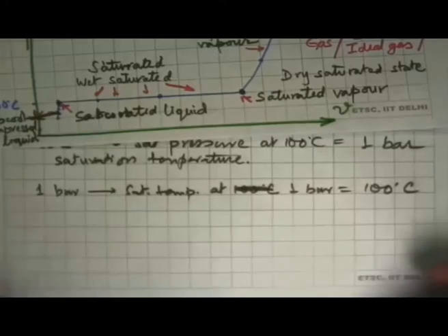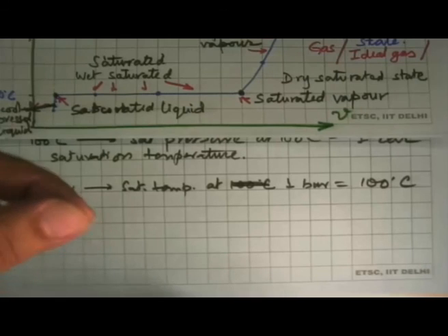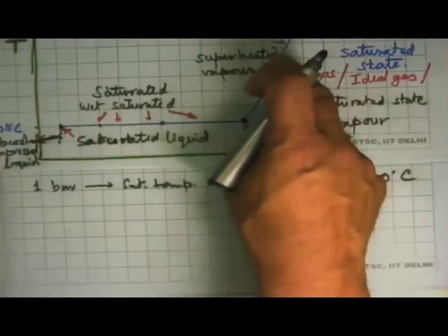And now we say, well, what happens in the other cases? So for this, one only needs to go to a table, and these properties are well documented, and you say, look, for this material, this is the pressure, this is the saturation temperature. And the pressure in this case is 1 bar. In a minute we will see what happens if it is 10 bar, 0.1 bar, or if the substance is different, everything will fall in place. What we will define now is, well, compared to the saturation properties, what can I say about subcooled and superheated states?